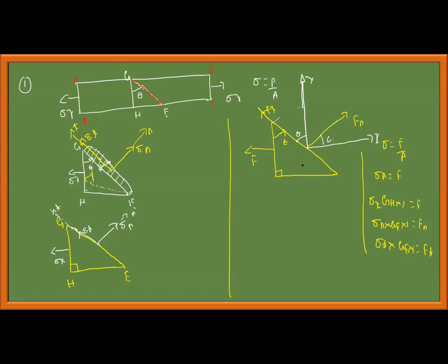So in order to know the stresses on this plane GE, I have two components: a normal component and a tangential component. Always the stress is defined with respect to the x and y axes, perpendicular to the surface. In this case, perpendicular to the face is sigma normal and the other axis is sigma tangential. Instead of x and y, for this inclined plane, it is sigma normal and sigma tangential.